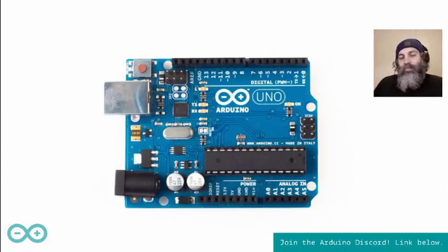And as you know, this board is an 8-bit microcontroller board that has 20 inputs and outputs. 6 of those pins can be used as analog inputs, and that's what we're going to be working with today, because we're going to be using one of those inputs as a way to detect that there is a signal coming in the microcontroller, and on the other hand we're using 3 digital pins that have the ability to write PWM, which is pulse width modulation, to control the intensity of light in 3 pins that are controlling an RGB LED.